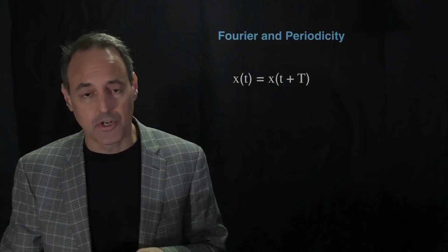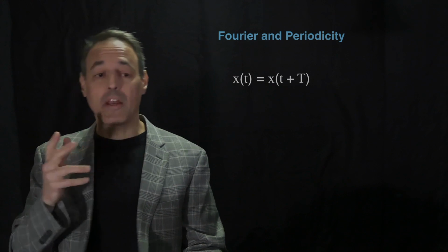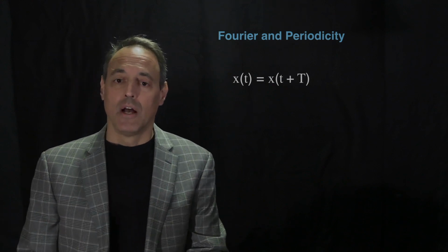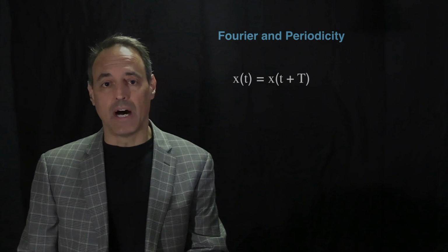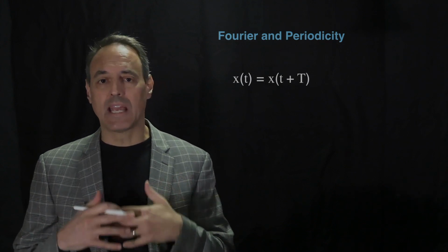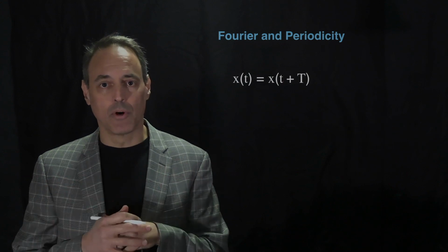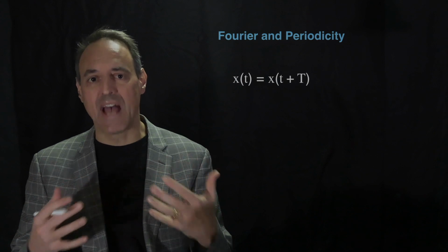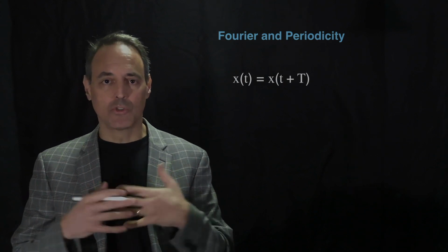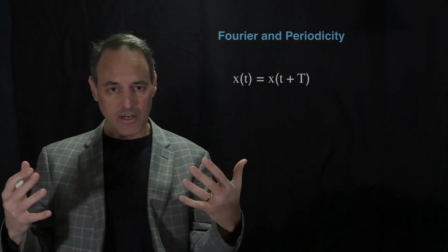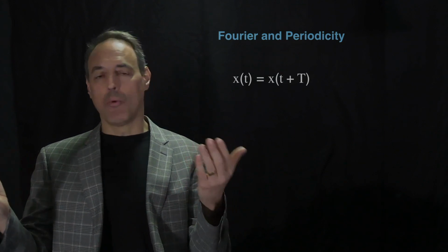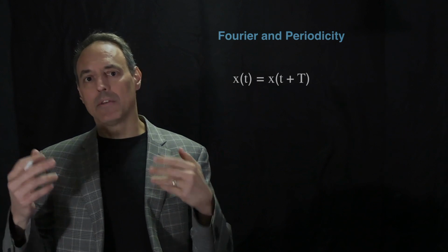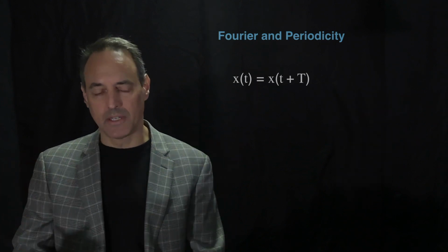So that's what we're going to focus our attention on now: what do we have to do to compute those coefficients, and how do we compute those eigenvalues. I want to generically take any signal and represent it as a sum of Fourier modes, and in fact that's exactly what Fourier was advocating. Once we can represent a signal generically as a sum of Fourier modes, then all we have to do at that point is figure out how much of each Fourier mode we have and what the eigenvalues are as it goes through our LTI system.